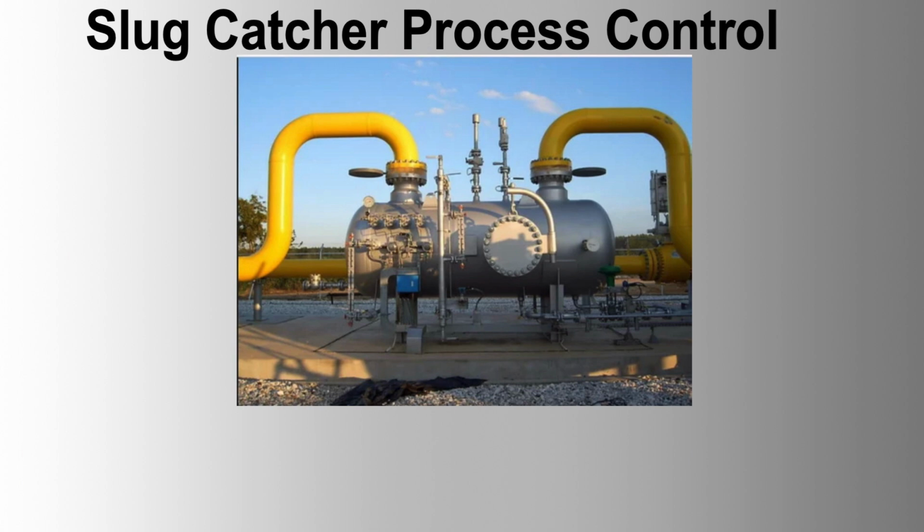Use a feed-forward controller to adjust liquid outlet valves based on anticipated liquid flow changes, and a feedback controller to fine-tune the liquid outlet valves based on real-time level data.